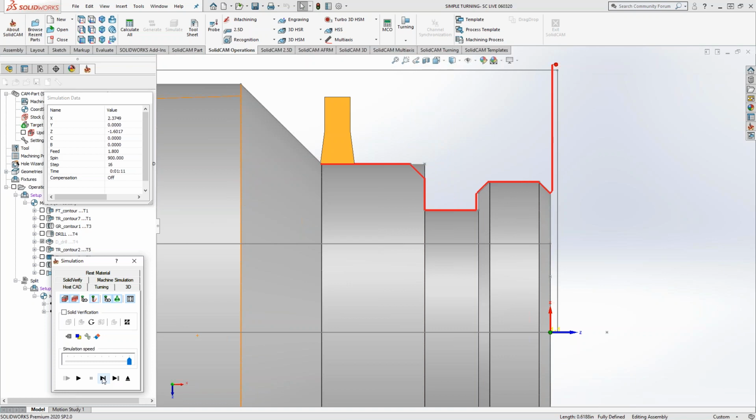Another example that was shown in the CAD/CAM night class was, like Kevin said, a double O-ring groove. You've got a custom tool with multiple inserts on it. How would you actually use that inside SolidCAM with the regular toolpath? You can't really do that. With manual turning, you can, only because you are accounting for the shape of your tool.